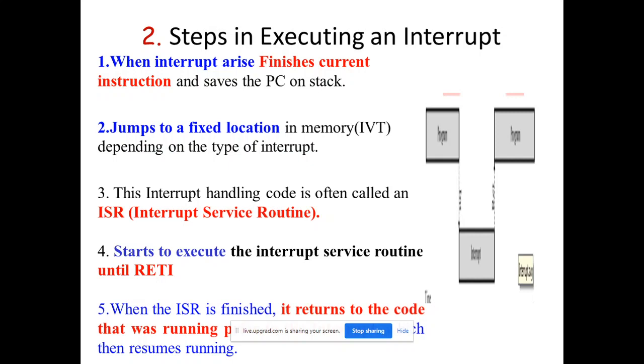In this fashion, when an interrupt arises, the controller will complete its current execution and save that location, for example 2000, on the stack. All of you agree with this? Stack is nothing but your memory location to hold the return address. In this case your address is 2000, and that is held on the stack.